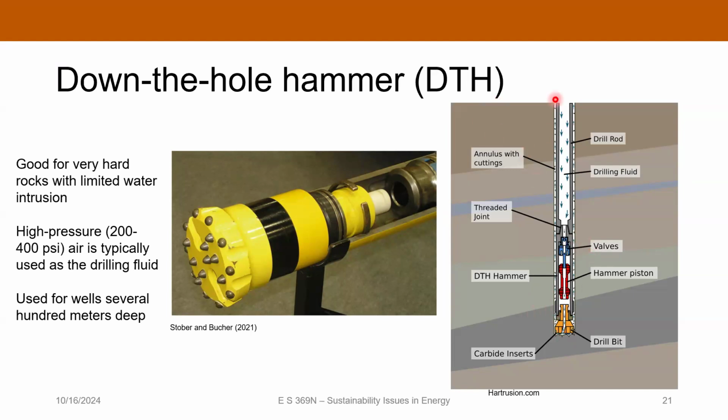And so you rely on some type of a drilling fluid to carry those cuttings back to the surface as you drill. And so this type of thing can work in wells that are up to a couple of hundred meters deep. You just need to have a pump at the surface that's capable of supplying the pressurized air to that type of depth. Eventually, you get to a depth where that's not possible. So this is another technique that's used, and this is fairly standard for drilling these couple of hundred meter deep geothermal wells.